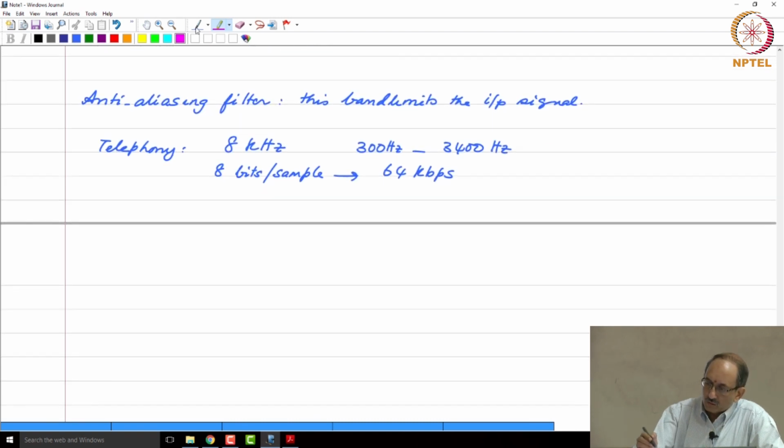Of course, now we do not use just plain sampling, we use speech coding. We take 30 milliseconds of speech, sample it, use a source filter model, and then transmit those parameters. The advantage is you get higher quality speech or a lower bit rate, but the price paid is more processing power. All this involves DSP processing. Anyway, coming back to sampling.